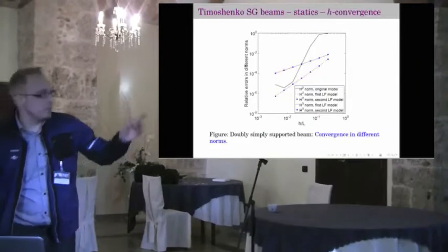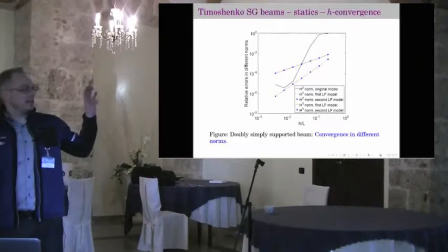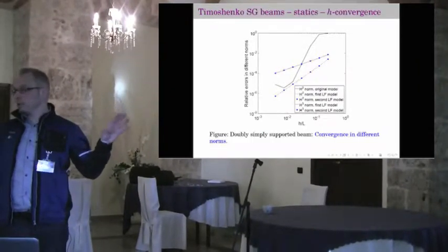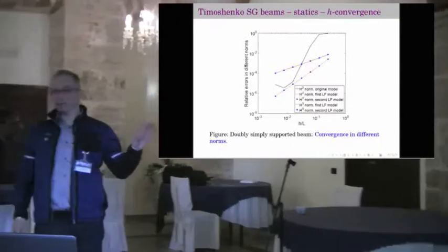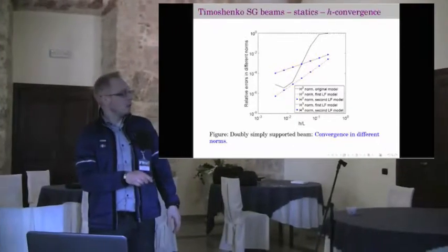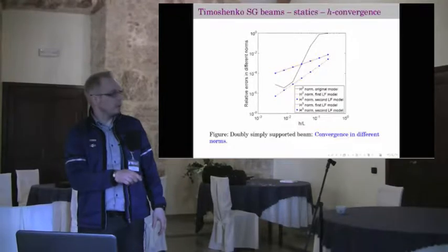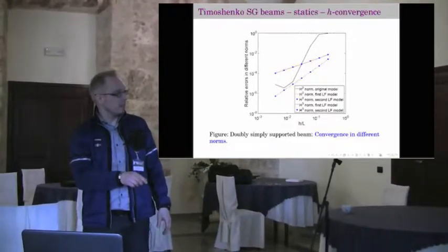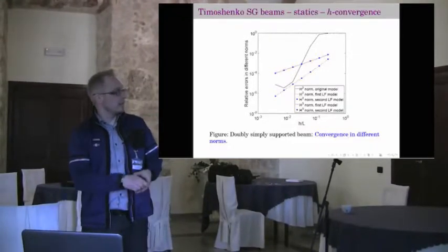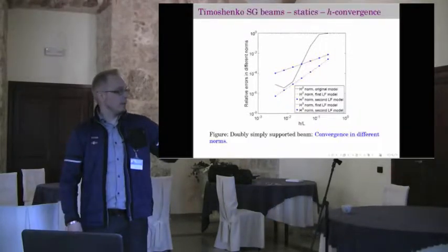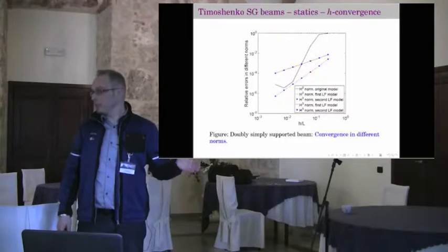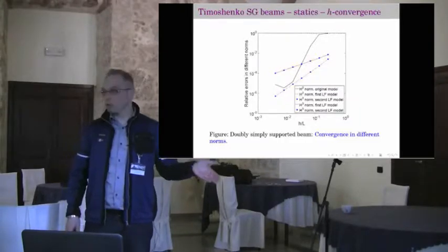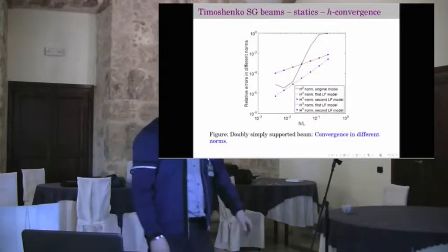And this is for the Timoshenko beam. You can see that in a very thin Timoshenko beam we have locking. This is the classical convergence result of the classical formulation. So we really start from a high error level, and then of course we refine and refine and refine. Then of course the error goes down, but it goes down non-optimally.